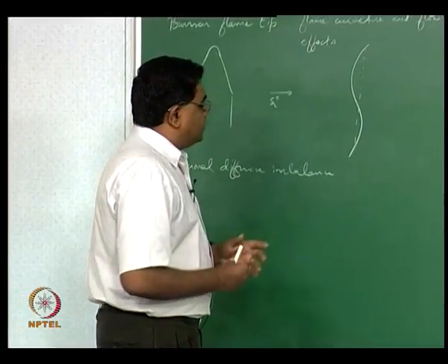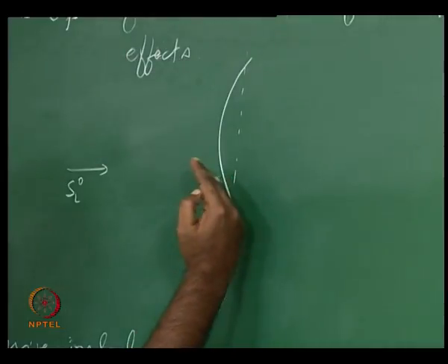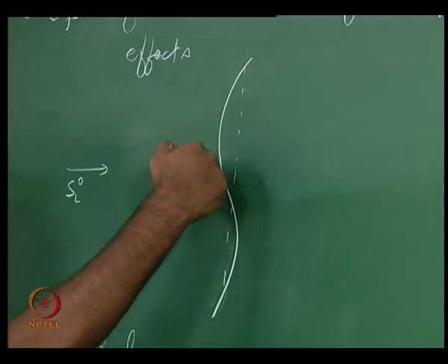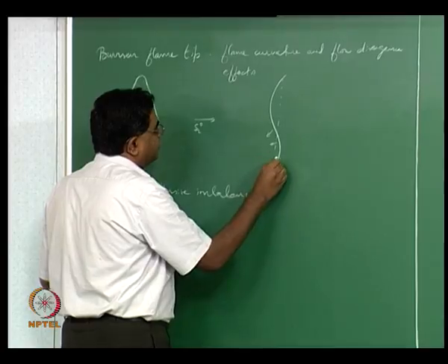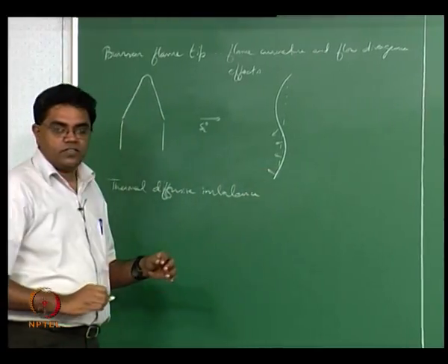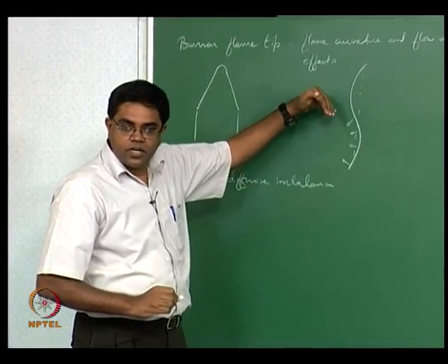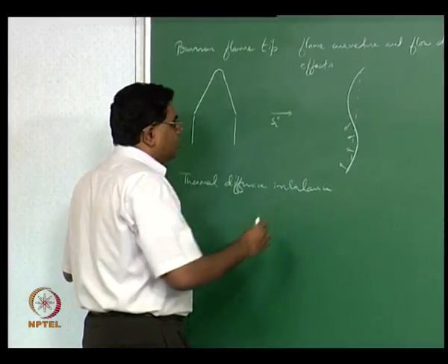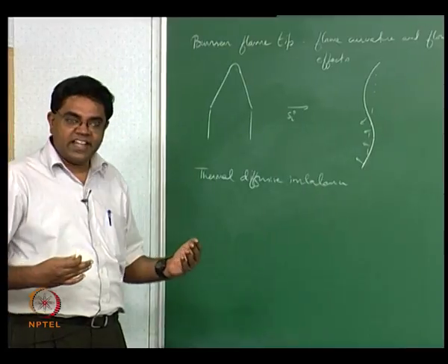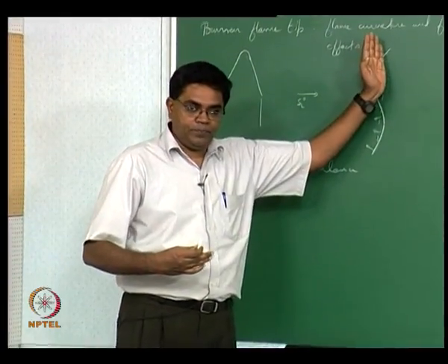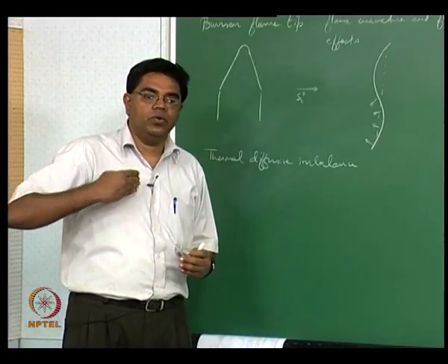What we now begin to see is, if you have a curvature like this, then beyond what is being heated for the cold reactants, you have a focused effect of heating the reactants. So the heat conduction becomes multidimensional, and therefore you are heating the reactants significantly more than if the flame were planar. This should give rise to a tendency for the flame speed to increase.